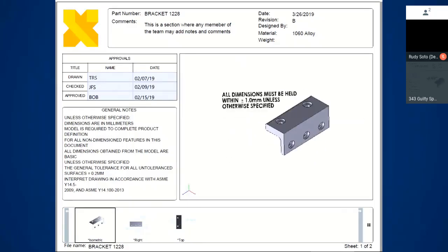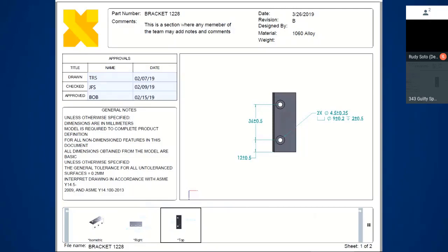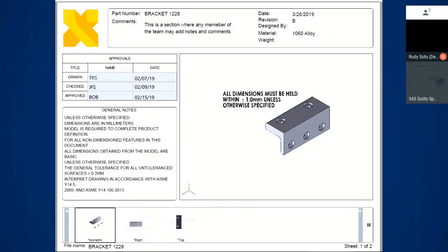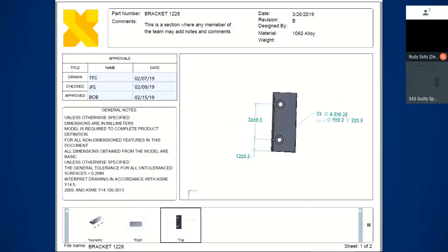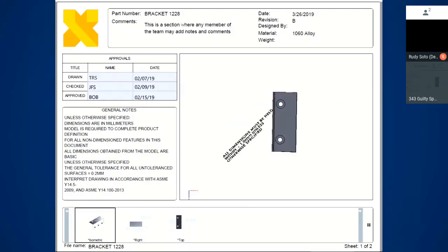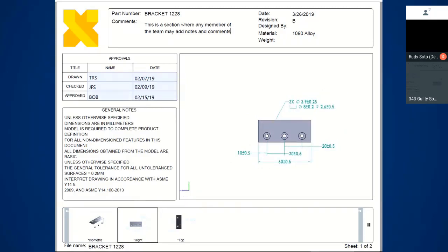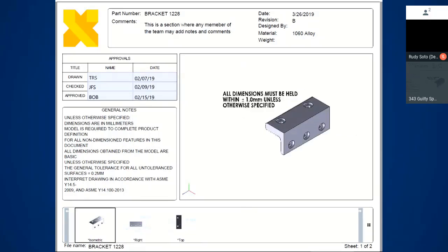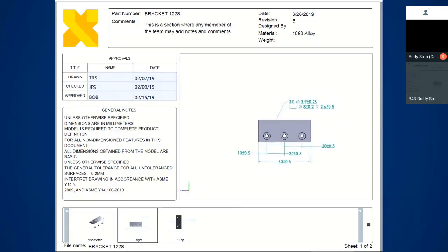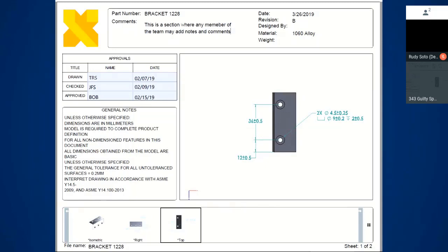Instead, we're giving the machinist a 3D CAD file, a step file, and we're specifying either in that step file or in some auxiliary file like this 3D PDF which dimensions are critical. And we're giving the machinist an overall standard beyond that, saying you need to hold your dimensions for this part within, for surface finishes, plus or minus 0.2 millimeters. There's a general note on the isometric view: plus or minus 1 millimeter, unless otherwise specified. Pretty loose tolerance on that one, huh?